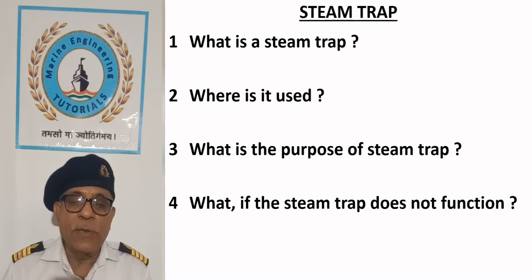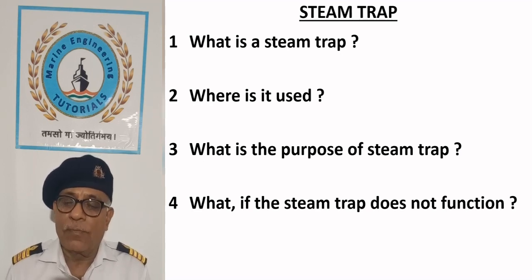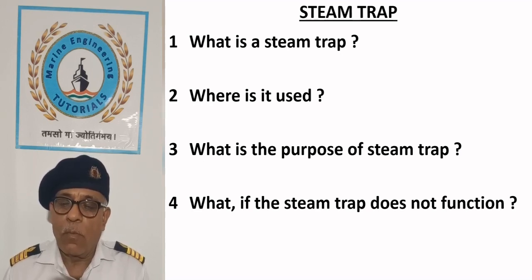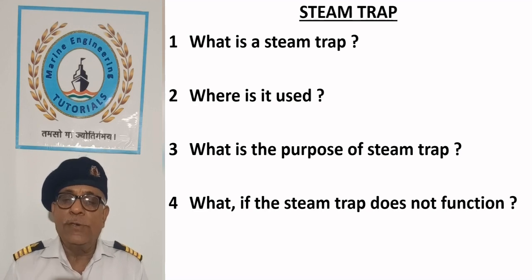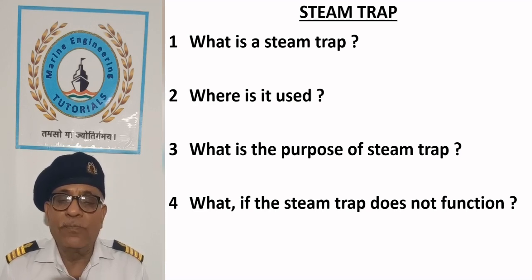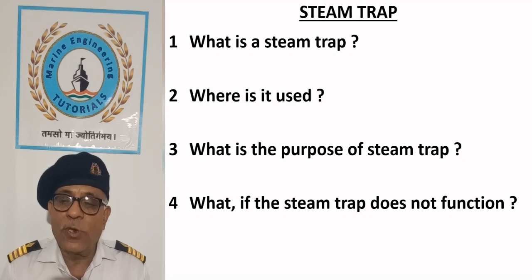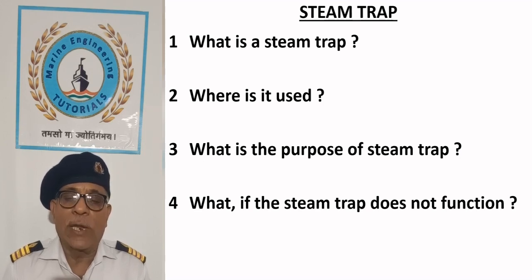What if the steam trap does not function? A faulty steam trap can cause reduced heat capacity of the heater. It is usually equipped with a bypass valve to control the flow of condensate manually.